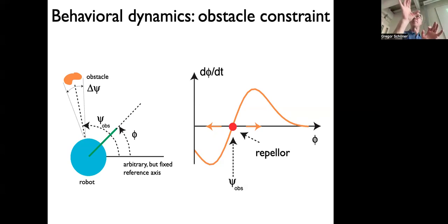So it will not be precisely the same function. It will be noisy. And that could mean that you're a little bit to the left or a little bit to the right in different moments in time. And that will make radical changes of your turning rate. So you'll be radically turning to the left, and the next moment radically to the right. You can see that would be awkward, right? The instability that's supposed to express a constraint would turn into a physical instability of the robot. It would be a bad idea.